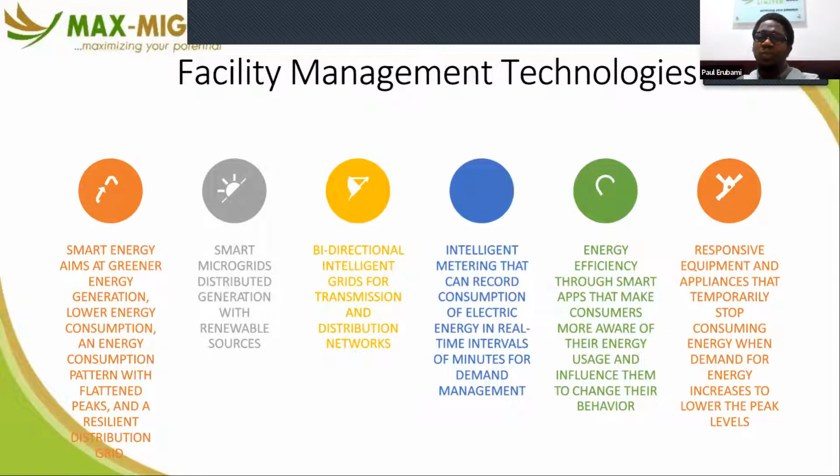You are giving the device information to say, this is what other assets in the facility are consuming at this time. Peak is getting reached. So if you can afford to knock off so you don't increase the peak, please knock off. And you tell that to all the devices and you put them in kind of a ranking order. So each one knows that when we are hitting the peak, there's preference or deference to certain assets that must be on at that peak time. The rest of them will, on their own, begin to knock off and give way, just to allow those that must run to run.